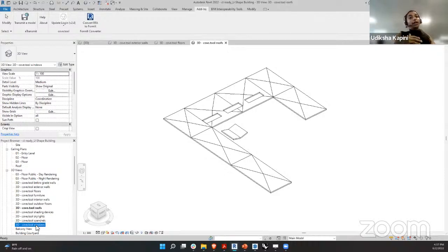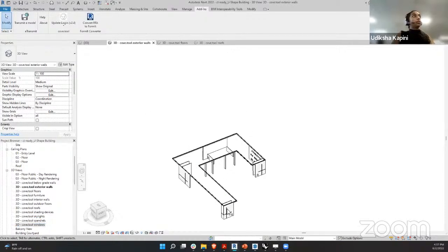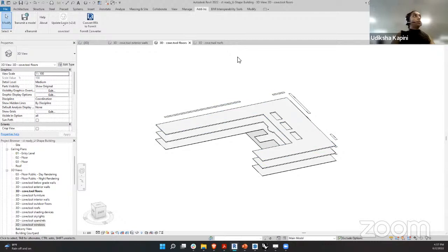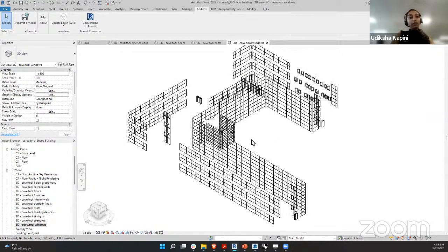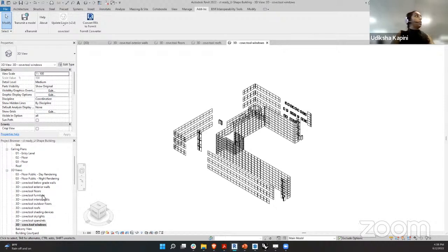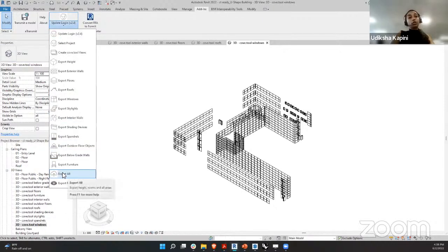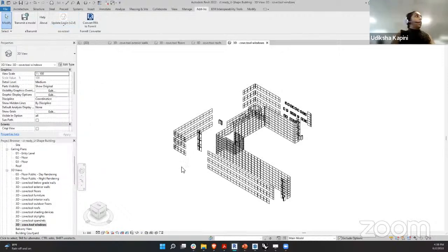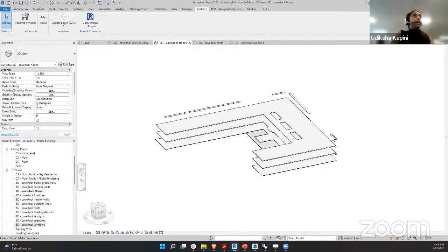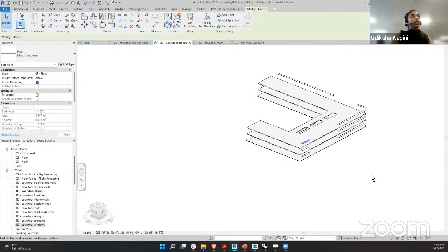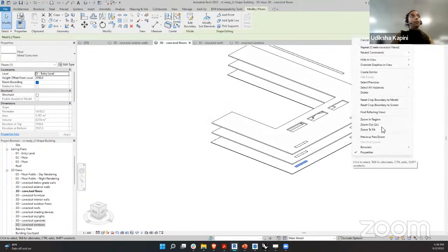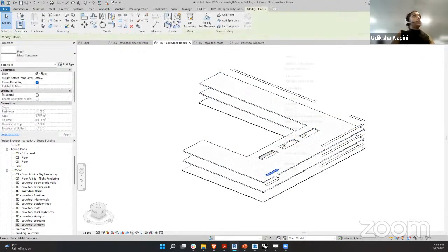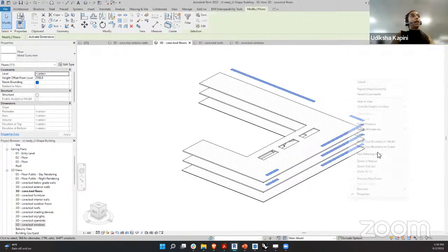And like we did mention earlier, we have 5 required categories, which means that we do need geometry that's coming in from your exterior wall view, your floor view, your roof view, and the windows view or your glazing. So once you have geometry that's been filtered in these Cove tool views, you are then ready to export all of this geometry on our platform. And if you do need to make any changes, you can simply do that by hiding these objects. For example, in this particular case, we have these overhangs, which are essentially not floor slabs, and we can actually benefit out of having them hidden in this view since they are not regularly occupied floor slabs. So all you would need to do in this case is select them and hide them in this view.